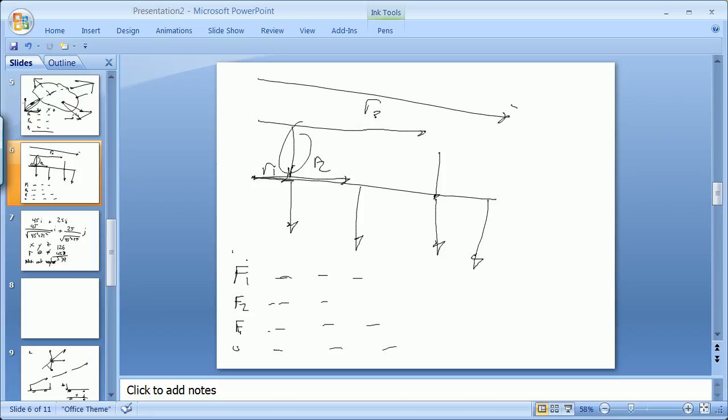But probably what you want to do is get in the habit of not doing this, but instead doing a table of the radial vector and the force vector. And so in this case, for the radial vector, positions 1, 2, 3, and 4, the radial vector will all be in x. There'll be nothing in the y, nothing in the z. For your force vectors, there will be nothing in the x. In this case, we're not dealing with z. So 0, 0, 0.